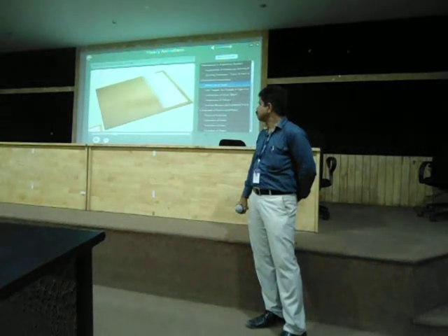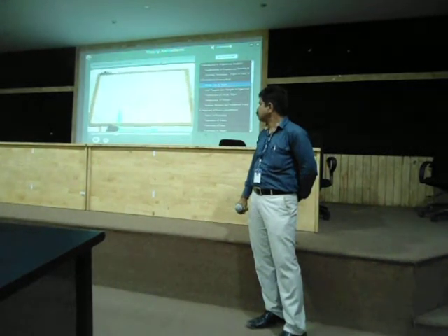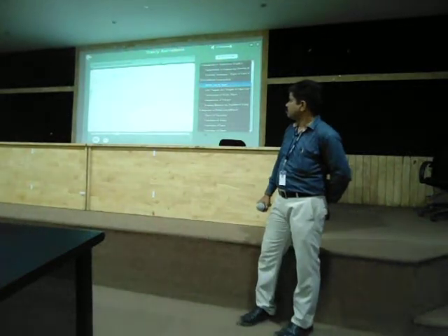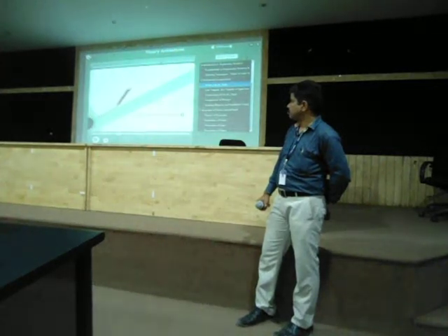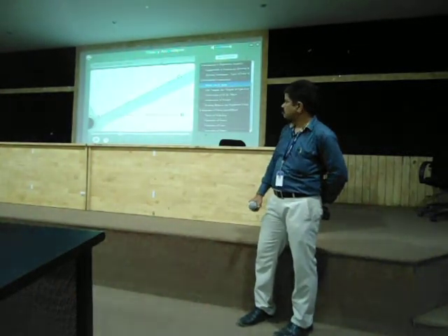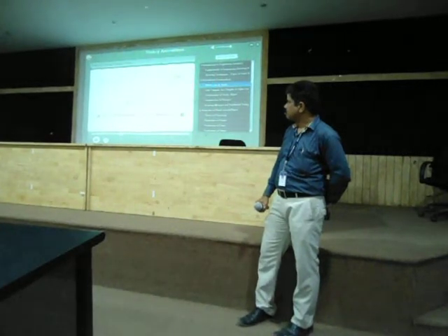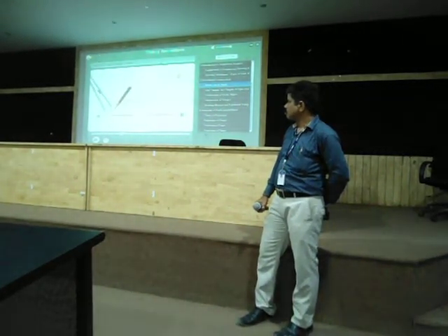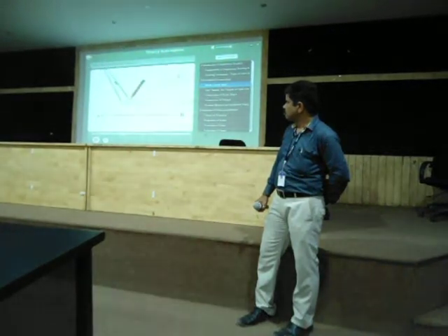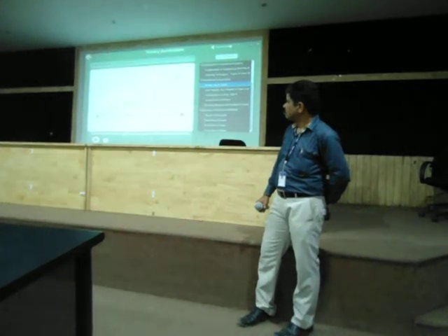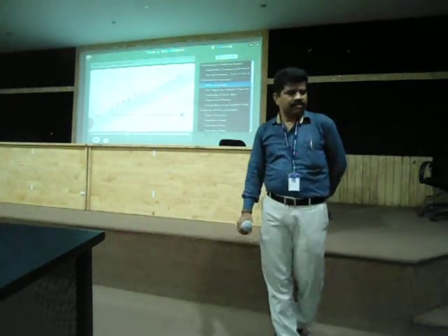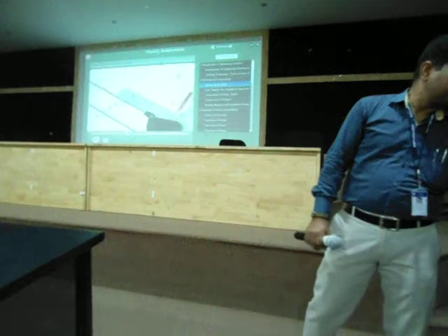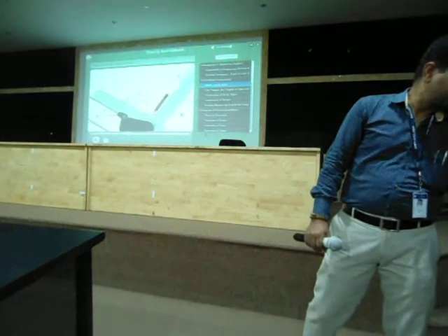All right. Now, we will take a look at how to divide a line into 7 equal parts. First, consider line AB of any length and draw line AC, making an angle of less than 30 degrees with AB. With the help of dividers, mark 7 equal parts of any suitable length on line AC and mark them by points 1 dash, 2 dash, 3 dash, 4 dash, 5 dash, 6 dash, and 7 dash. Join point 7 dash with point B of the line AB and draw.